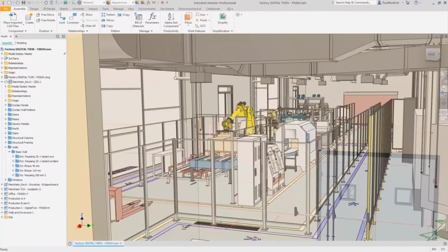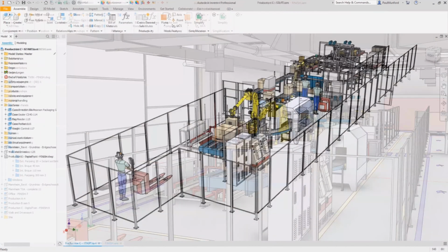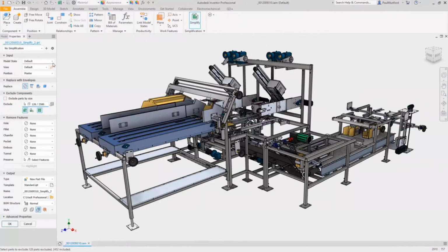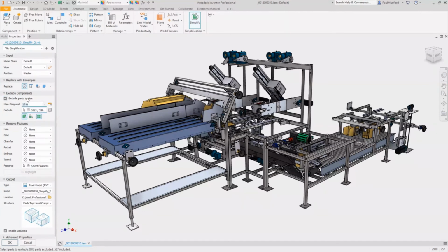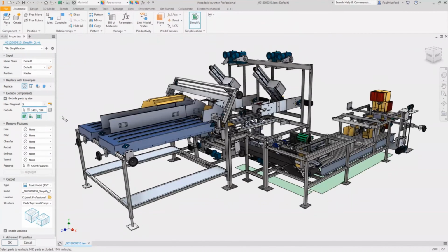Now our design's complete, we can share that model for our design and Revit user coordination. By saving our Inventor assembly as a Revit model, we'd like to remove manufacturing detail from the design, which is unnecessary, obviously, for the display. But for coordination on a BIM project, a newly laid out simplification dialog helps us automatically remove components from our design by feature size.